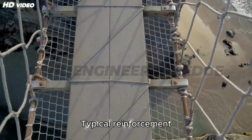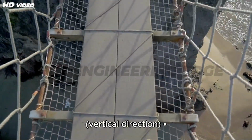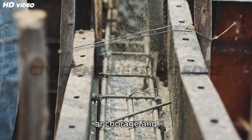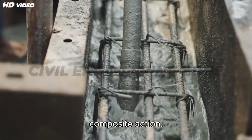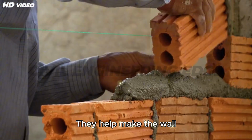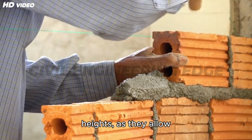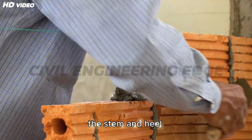Typical reinforcement includes main bars along the vertical length, and stirrups or ties across the width. Proper anchorage and development length are essential to ensure composite action. They help make the wall more economical, especially at greater heights, as they allow for reduced thickness of other components like the stem and heel.